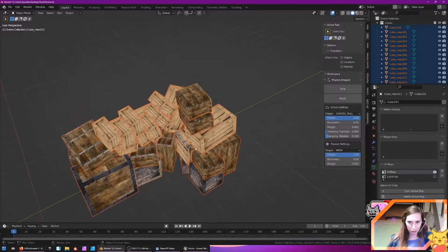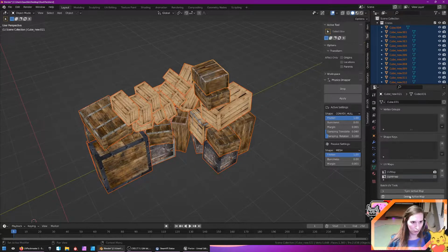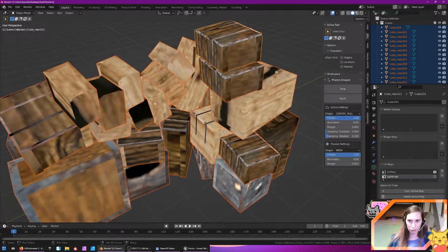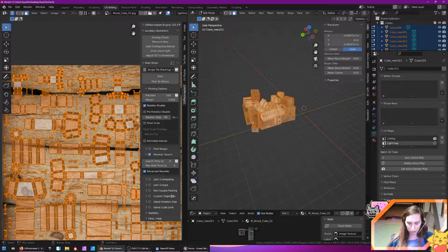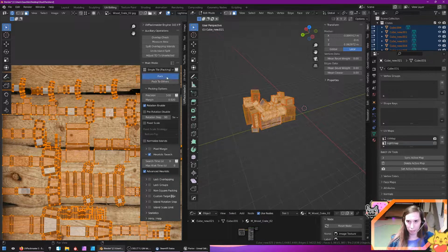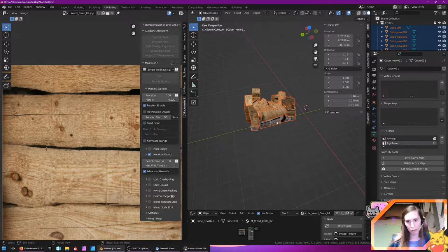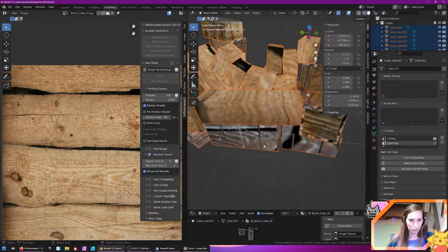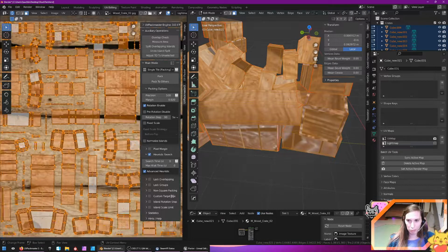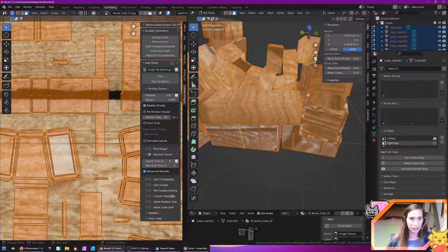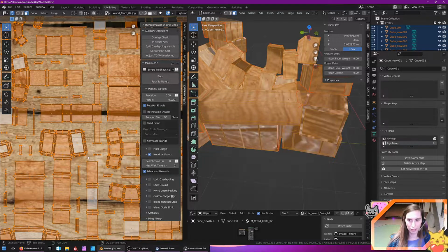And every time you change something, of course, you have to create the light map UV new. So set all to the light map UVs, UV editing, unwrap, and pack it. And if you do it like this, you always have some nice packages. So you have low mesh count, low draw call count, and it will bake very well. And with this method, there is guarantee that you have 0 overlaps when baking the lighting in Unreal.